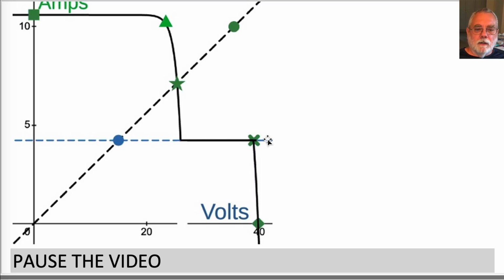Near the green X mark operating point, a local maximum power point for this case, the partially shaded solar cell could be sourcing or dissipating a small amount of power, and that string's bypass diode would be off. But the bypass diode does no harm in this case. I don't have enough information to know how a particular microinverter or DC power optimizer will behave in this case.